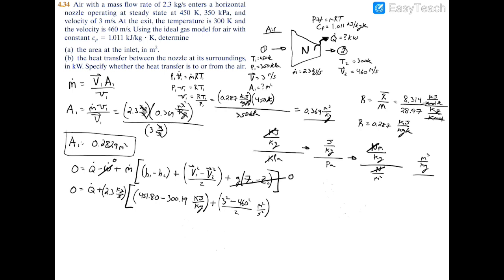And before we close our final bracket there, I just want to make sure that we're adding apples to apples here, because you can't add x to y, but you can add x to x. So we have to make sure that our unit here and our unit here are both consistent. So what is a kilojoule per kilogram? Well, a kilojoule is a kilonewton meter, and then you're dividing it by your kilogram. And from Newton's second law, what's a Newton? A Newton is a kilogram meter per second squared. So we're just going to multiply that by the kilo prefix and divide by kilograms. So all I did was replace that Newton with this expression here.